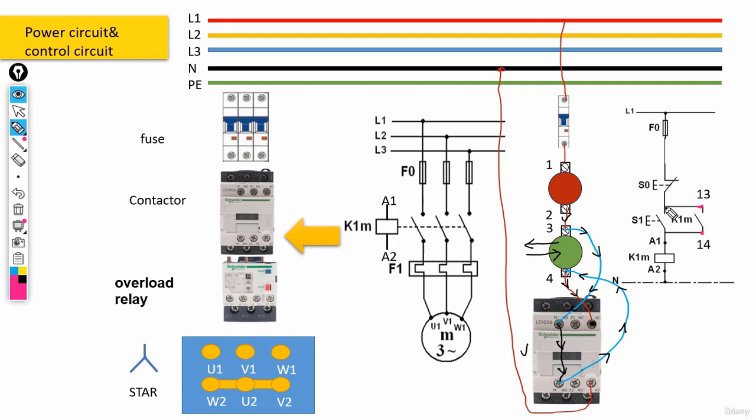And they are connected to the contacts 3 and 4 in our start push button. And somehow created an alternative path for our electrical current. And well, as I said, this would turn on the contactor, but this time it would be permanent.